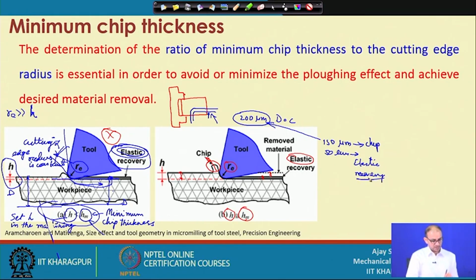Okay. So, now what is happening, that now you have 2 constant depth of cut, that 2 cycles of 200 micron of depth of cut. So, in the first cycle we have given this command, and unfortunately this 50 micron is still available there, only 150 micron is removed, but we do not know during the machining that this has happened. Now, first cycle is over, you are going for the second cycle.